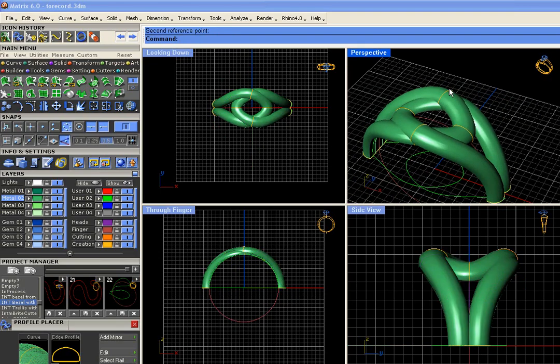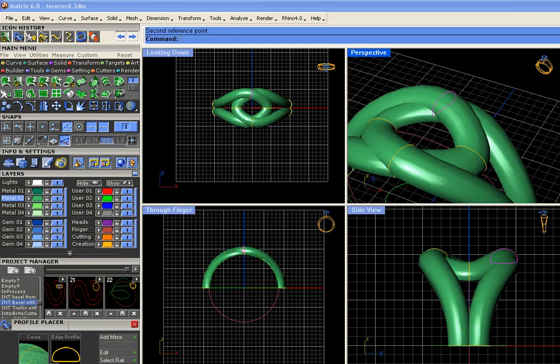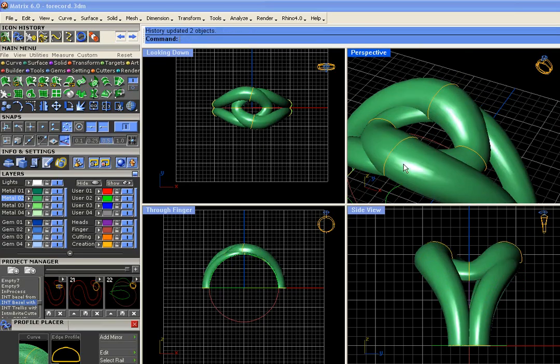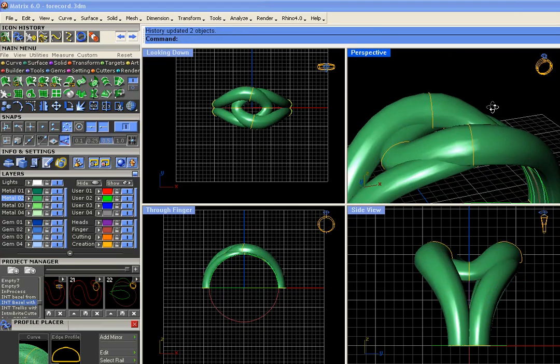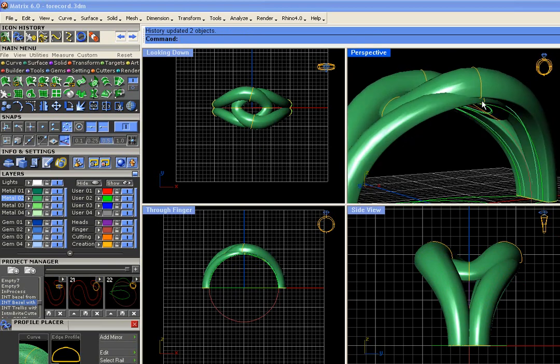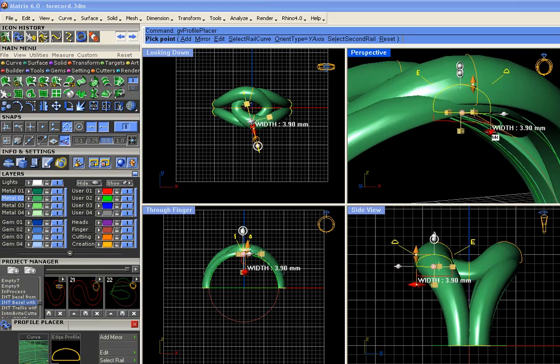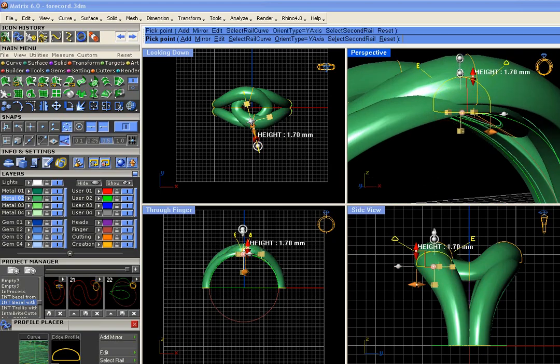Now, all I have to do is edit the original side. Now, keep an eye on this one. That's its counterpart over there, right? So F6, MSR, enter. And they'll both grow. Okay? So if you turn on Rhino history and you want to use it with matrix history, just beware. It might do funky things, but it can also work in your favor as well.